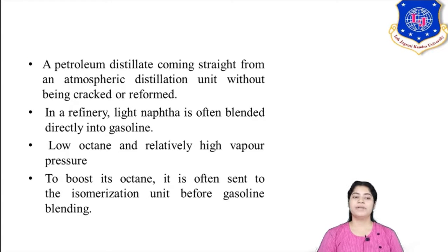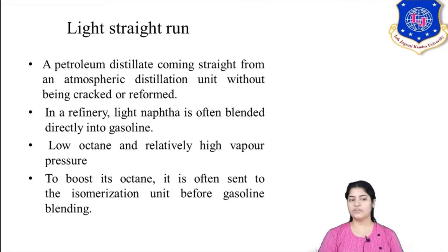Now, a petroleum distillate coming straight from an atmospheric distillation unit without being cracked or reformed is called light straight run naphtha, LSR naphtha. It is a form of gasoline. From the name itself, straight run: the first fraction which you obtain from the distillation unit is your light straight run naphtha. It is often blended directly into gasoline. It is used as a blend.